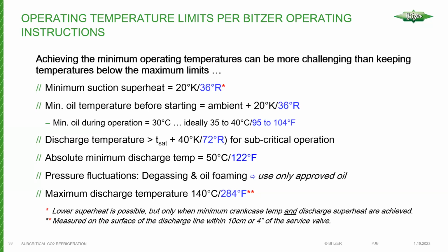And I get asked the question, by the way, about crankcase heaters. If you have equipment indoors, do we need crankcase heaters on systems? Whether they're HFC systems or CO2 systems, absolutely. And you'll find in instructions, I think in the Bitzer instructions, that if you're below a certain charge level, you could in theory get away without a heater. I'm a big advocate for heaters. Generally speaking, you want to have crankcase heaters on the oil to limit the amount of refrigerant that's going to end up in that oil.